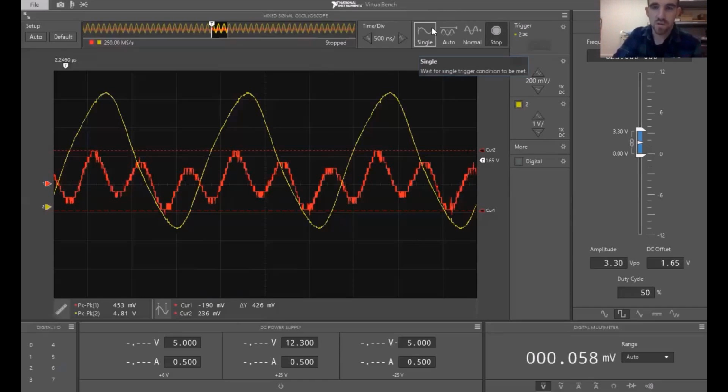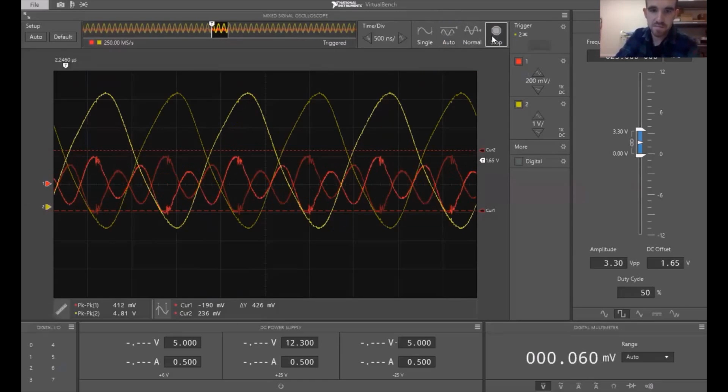And if you want to see it with the eye diagram, I'll stop this. And it's approximately 400 millivolts. So this just kind of shows you the effect of capacitive and inductive coupling as you go down the line, and also how the harmonics increase. Crosstalk also decreases the eye width and the eye height as well.